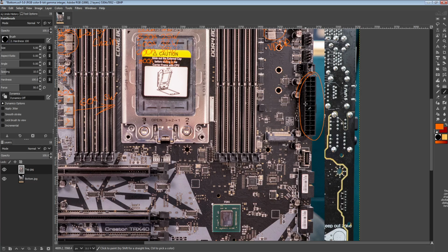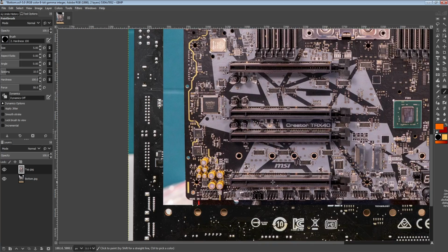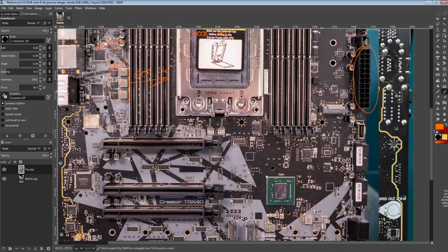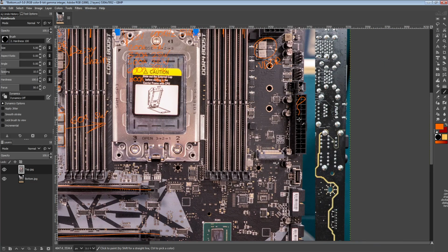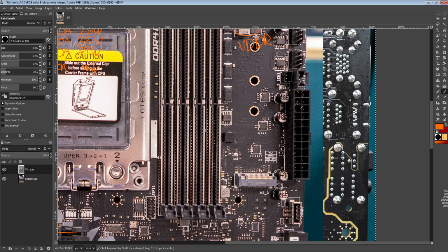Once you hit 4 GPUs, the 24-pin is just straight up unacceptable, but this motherboard really isn't laid out for a 4 GPU setup, so that's not really a concern. But with 3 GPUs, you'd go here, here, and here, and it's just like, will the 24-pin handle it, especially because MSI is again using folded metal pins? That's not great.